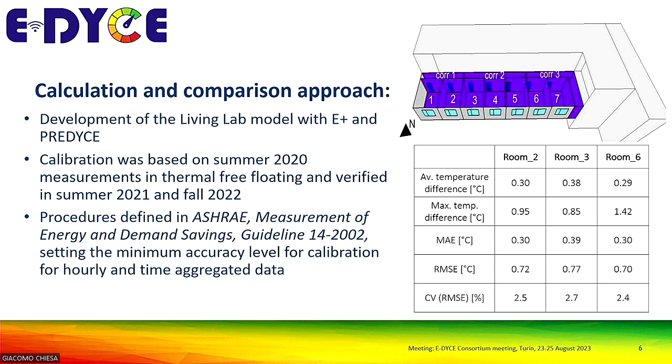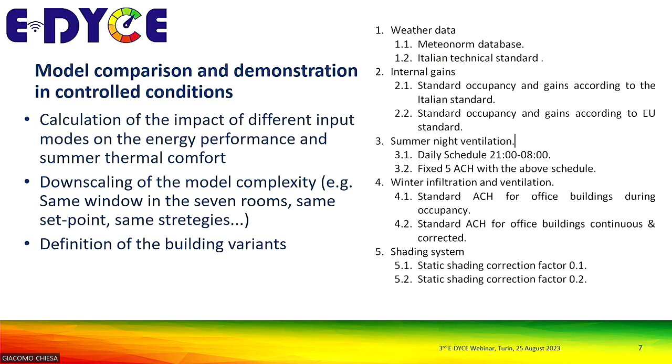Once the model was fully calibrated in thermal free floating and with active energy system, we started with our calculation exercise. Just to remind, I didn't say before that we have excellent results in terms of thermal free floating, while with active system we scored a performance gap in the heating and cooling mode of around 10%, but we will come later to this, which is anyway in compliance with the guideline of ASHRAE.